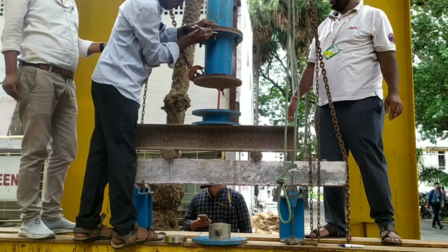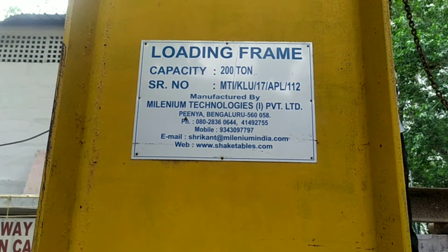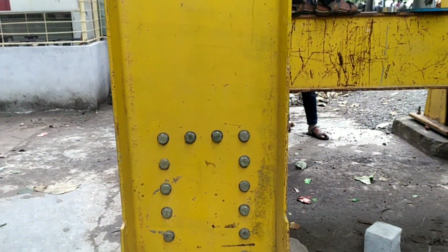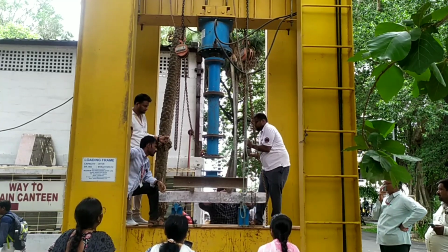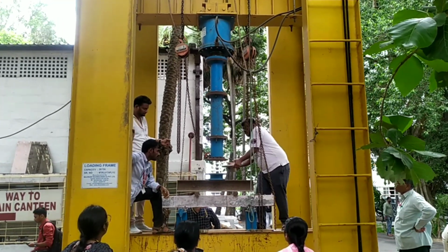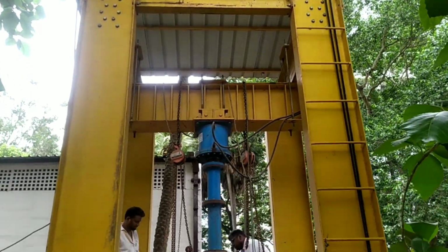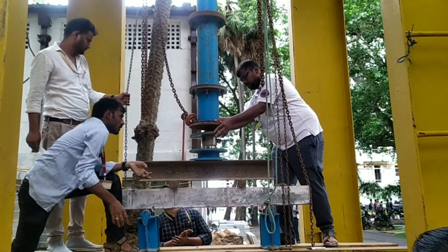At the different loading rates, the vertical cracks which are seen on the bottom of the beam were caused by tensile failure of concrete. By careful observation and comparison, the width of the cracks decreased with increasing loading rates and they were distributed more uniformly.